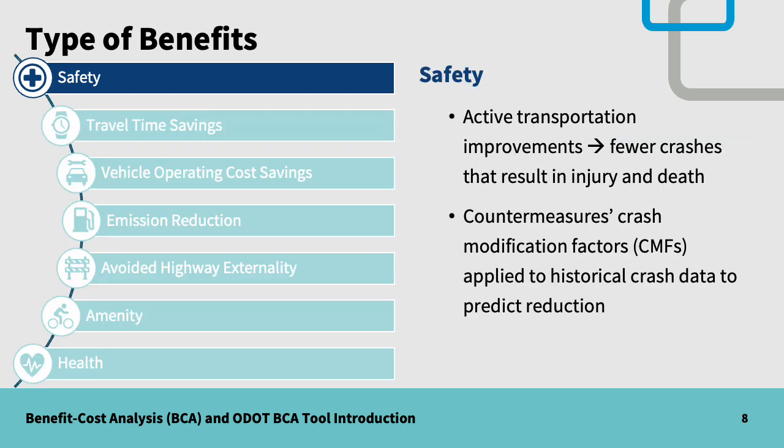Safety. Certain infrastructure improvements have a demonstrated effect in reducing crashes and injuries. This tool uses a crash modification factor, CMF, to estimate this reduction, and then we value this benefit in dollar terms, as with all of the following benefits.